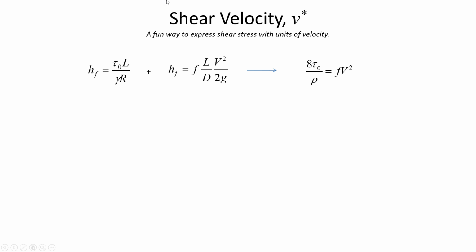So if we take this definition of head loss due to pipe friction in terms of shear stress, and we worked with this first formula a little bit in our first 2 class meetings, the idea is that when water is flowing through a conduit, whether it's a pipe that's enclosed or a channel that's open, either way, the stationary material that isn't moving, meaning like the concrete of the channel or the pipe material, is stationary and it's resisting flow. And it resists it by applying a shear stress to the fluid. So that's what this is.